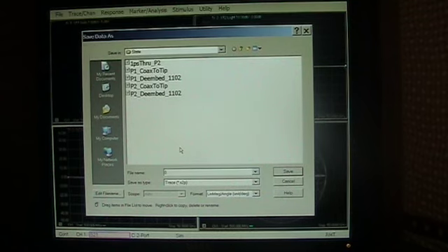We'll call it 0 picosecond through from 2 to 50, 1102. Our on-wafer standards actually have no electrical length to them. We shorten the length in order to eliminate that. So nevertheless, we're going to save this scattering parameter file as the 0 picosecond through path.